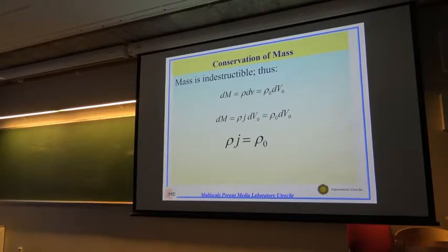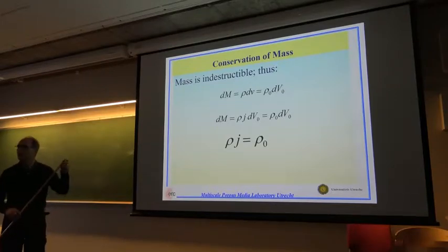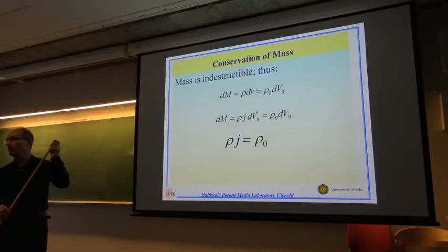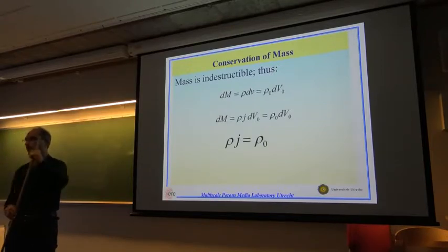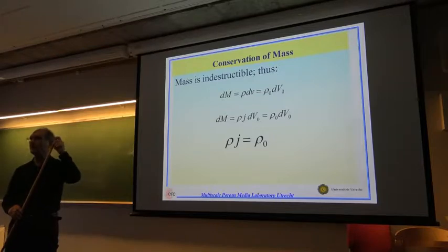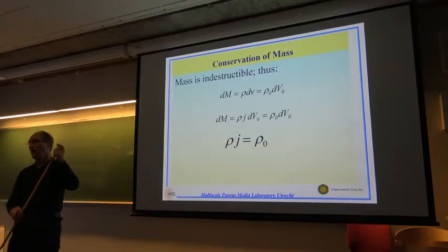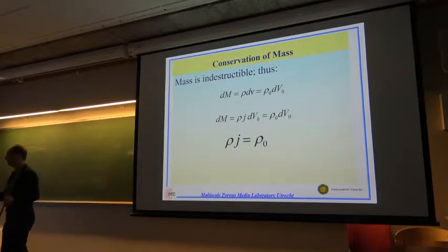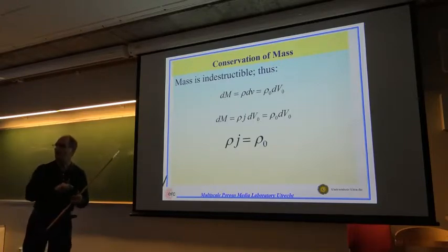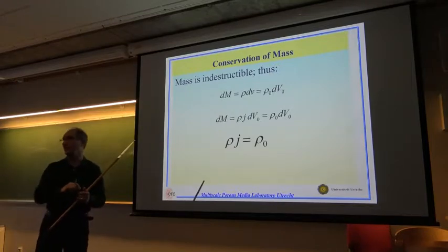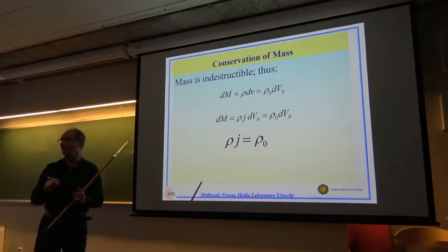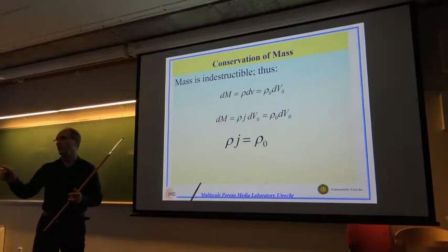Okay. Can I just ask one thing about the F, so this transformation? In general, this is a matrix. When you take the gradient, it's a matrix. But you don't seem to distinguish explicitly between the symmetric and anti-symmetric part of that matrix. Oh, definitely. It exists. That's sure. That's why we define this Cauchy strain tensor. Yeah, strain tensor, which is symmetric. Exactly. So that's symmetric, and then you get rid of the problem with the rotation we referred to before.